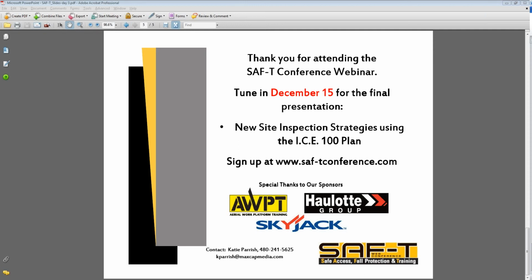In some boom lifts, yes, and obviously that depends from lift to lift. Capacities of any aerial lift are based on the manufacturer's design and testing of that lift to meet the requirements and the standards that are applicable. But certainly there are boom lifts out there that have a capacity of 1,000 pounds as rated by the manufacturer, and if the manufacturer has rated them and they are compliant with the standards, which there are, again, I'm not trying to say people aren't compliant with standards, so there are boom lifts that are realistically and safely 1,000-pound capacity machines.